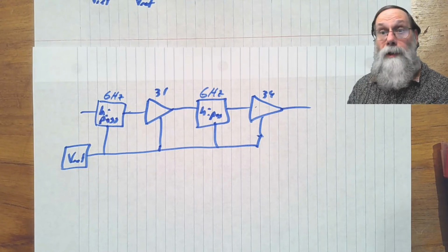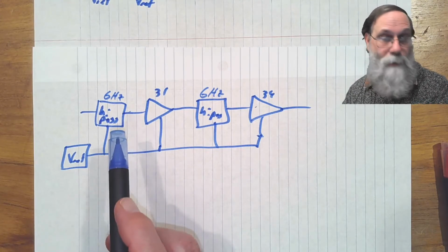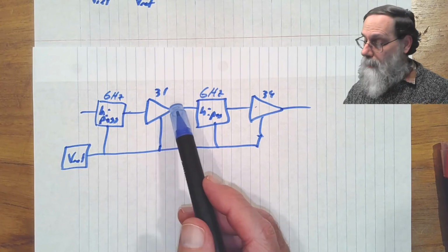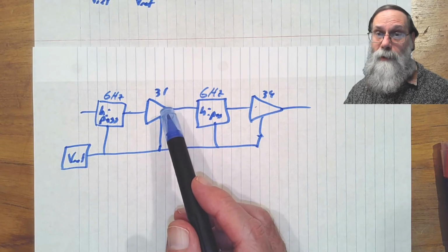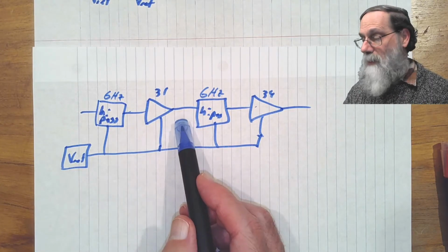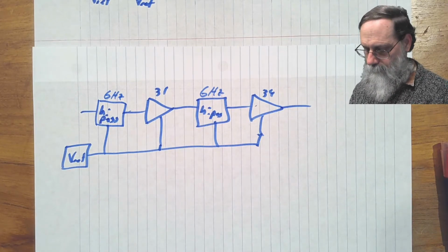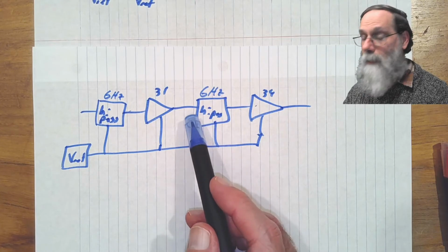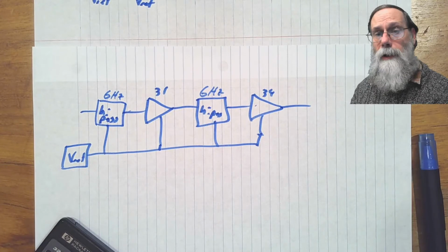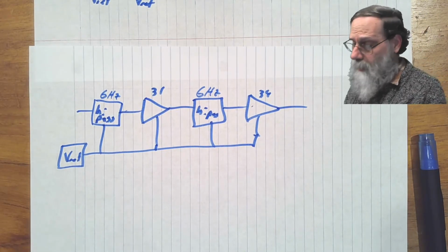All right, what is this doing? Well, we had a plus or minus 4 millivolt offset here, which got multiplied by this times 31 here. But that wasn't enough to cause this thing to clip. So it just gives us, what's 4 times 31? 124 millivolt offset here. It's actually a good idea to write all these things down, because one of the things about a block diagram, it's not enough just to tell what the blocks are. You have to say what the signals are.